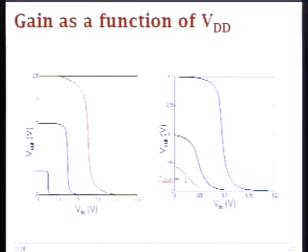What that causes is that you are no longer as immune to external noise sources as you were for high VDD, because your external noise sources do not scale with supply voltage, so you get hurt in that case. And you can still keep decreasing voltage below the threshold when you have sub-threshold operation, but you soon hit a fundamental limit.